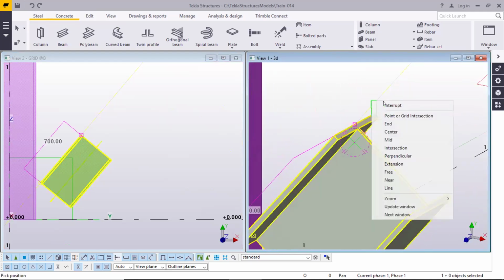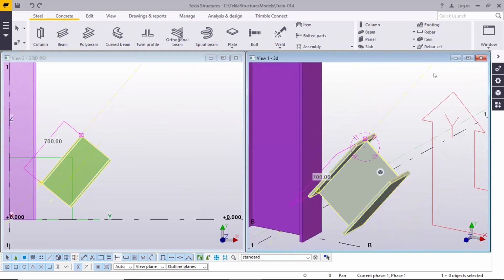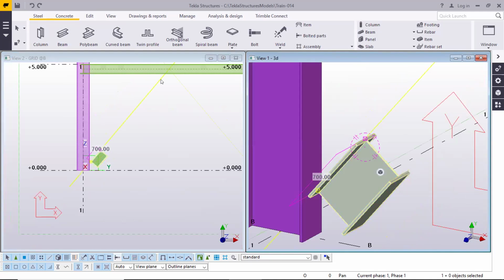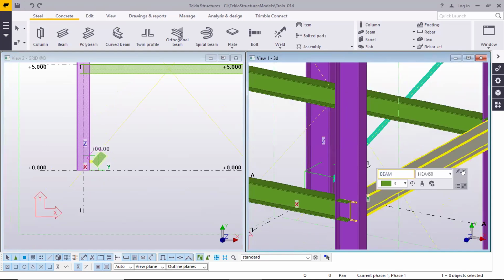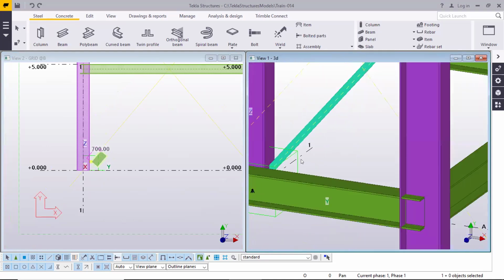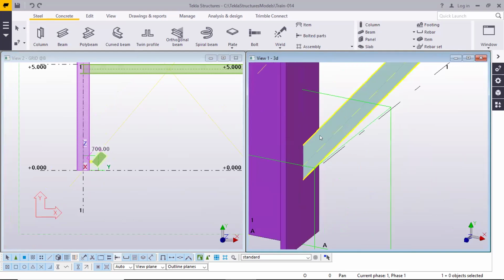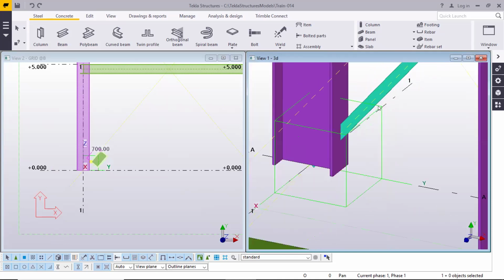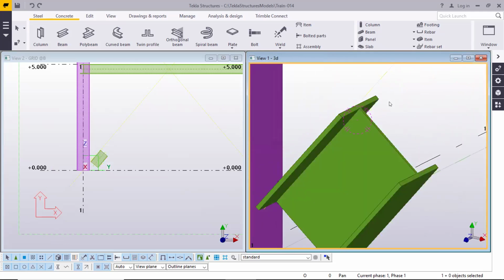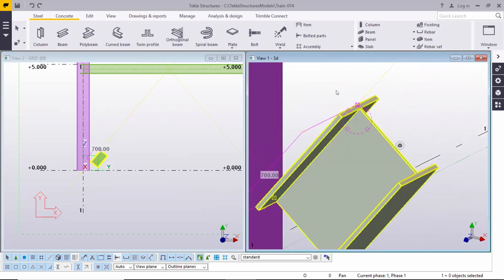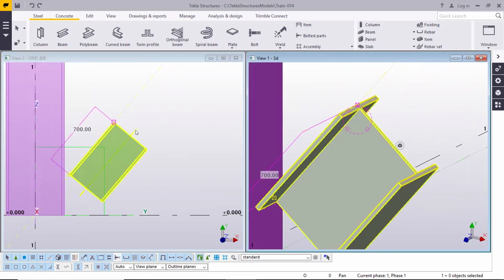When you are adding a big member from here to there, a total length member like this, what will happen? When I am here, I will not be able to see the position of the angle. So that's why I'm adding a small piece. When I'm zooming here, I'll be able to see the rotation, what rotation is there for this particular section. So that's why a small piece.